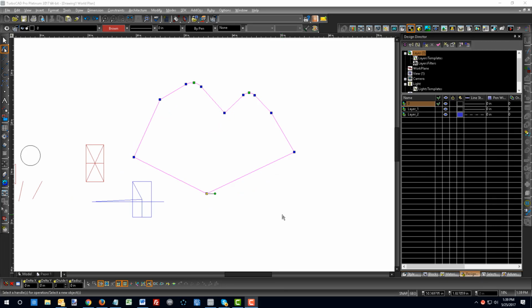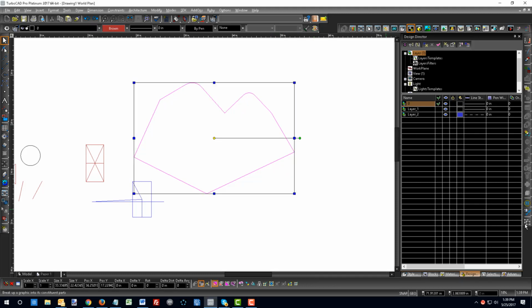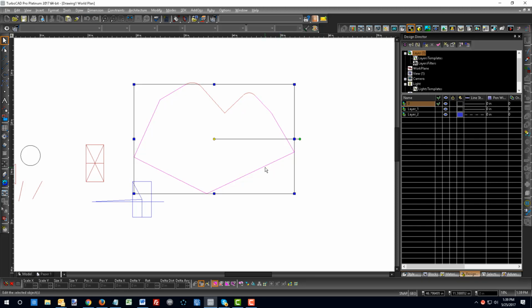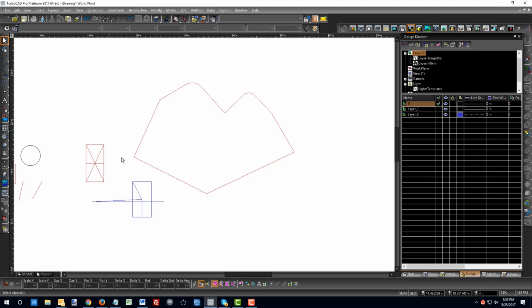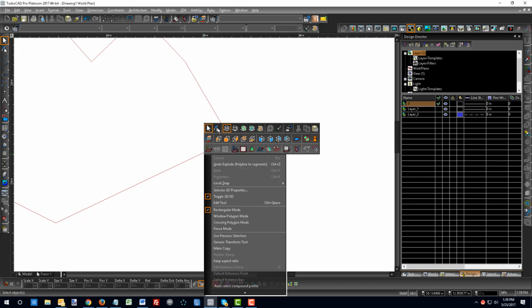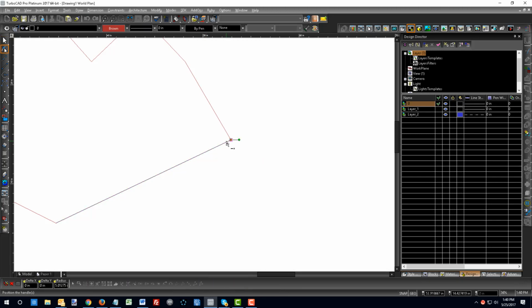Okay, one final point on polylines in general. What I'm going to do next is select this and explode it, and this is going to break this polyline into a series of segments and arcs, and if I do it one more time here, it'll break it down even farther. So these are now individual line and arc segments, and in a lot of cases geometry will be drawn using a combination of lines and arcs, and if you're not careful, what can happen here, and what I'm going to do is take one of these nodes and slightly displace it.